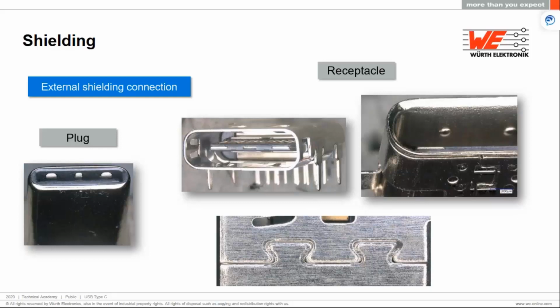Steel is considered to be a very efficient material and one of the best for mechanical holding. And that is why this kind of a material is preferred while designing a USB plug and receptacle. All the 4 points are required for shielding according to the guidelines. We provide 6 points or sometimes even more to provide a better stability and better shielding. The more contacts you have, obviously, the better shielding can be assured.